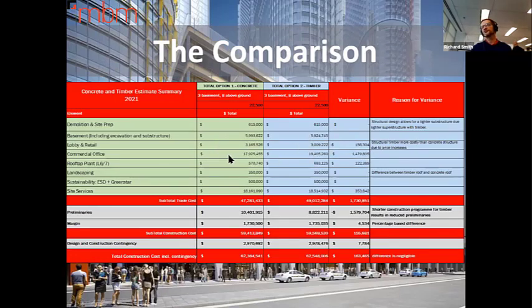You've got that superstructure, the commercial office tower, where you've got the $1.5 million premium for the timber and a $1.5 million saving on the timber as well. So I think all that data, when analysed for me as a QS, tells me that even timber in its worst profile that it's been in a while, simply because of that supply and demand pinch point, can still compete with traditional construction. What it also tells me is that even though this is a fiercely competitive market at the minute, it's only so low that concrete construction can go, right?